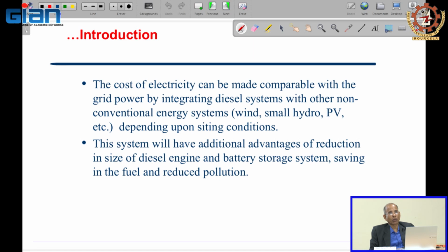In that case, if you have electrical tube lights, you have this choke. The choke will also produce a humming noise. So they will make provision that all the electrical chokes will be placed outside the room. Okay. So depending upon what kind of application you are designing, noise could be one of the concerns.